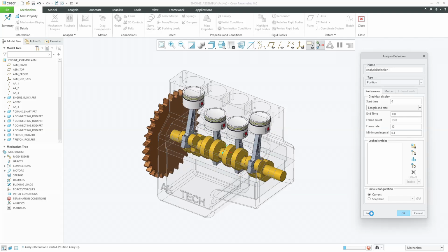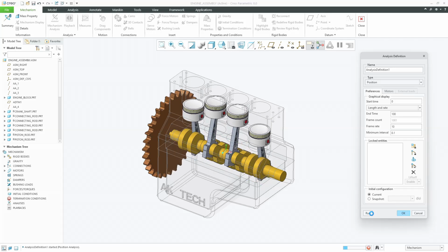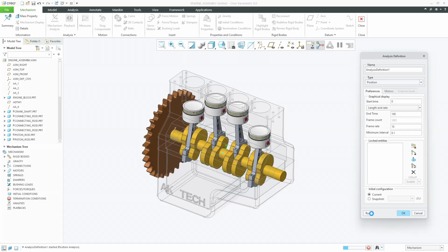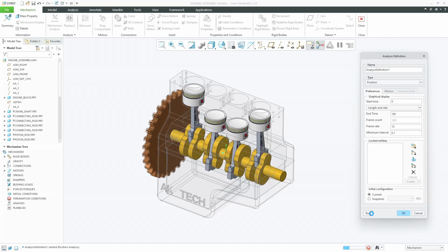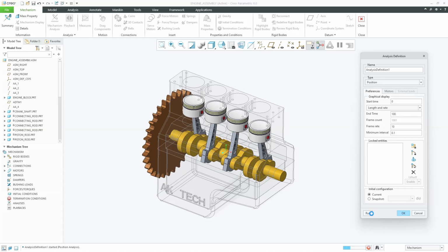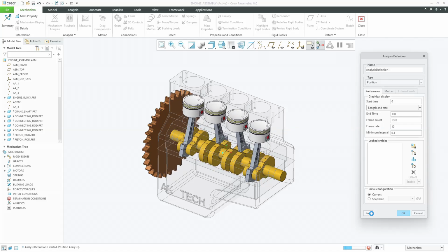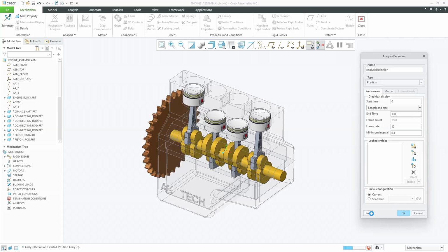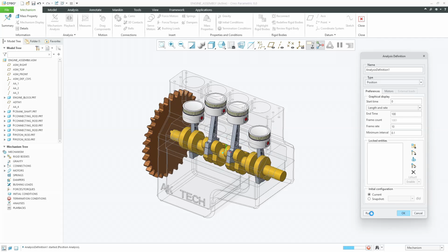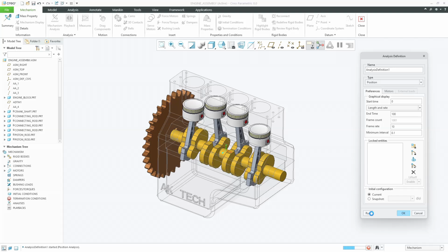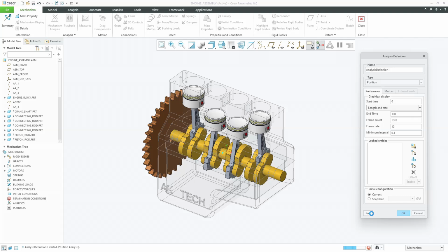So this is going to run for 100 frames. Since the velocity I have given is 25 degrees per second, it will be a very minimal speed. Once it's done, I will change the velocity value from 25 to some other value, and I will showcase how the gear mechanism will work. Let it run for a minute. Within a minute, this mechanism run will be done.